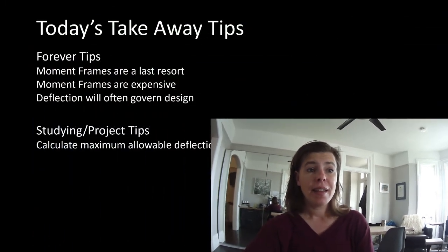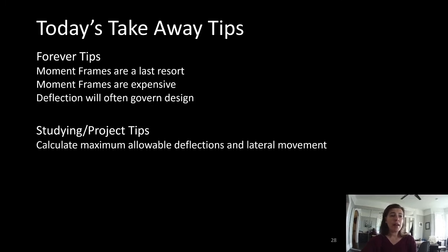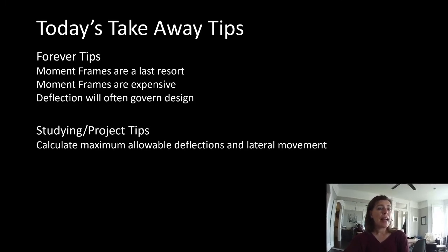So in summary, I'm super proud of you guys, and I think what you are doing is amazing in these crazy trying times. Quick summary of this lecture. Moment frames: last resort. We don't like them, they're expensive, they're not easy to do, and deflection will often govern the design. We should know how to calculate maximum allowable deflections and lateral movements of buildings and elements. And then the rest of what we did today was examples.